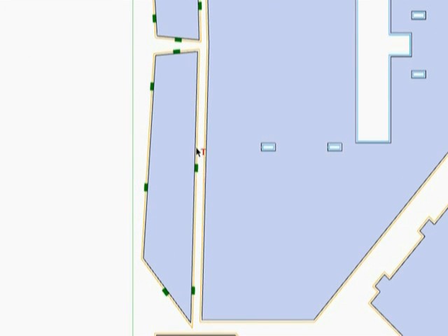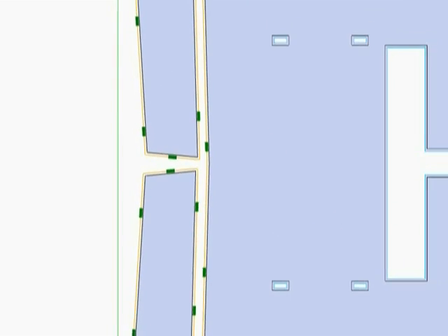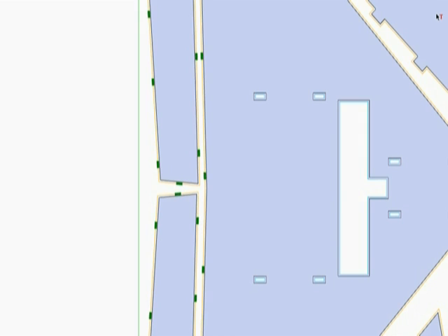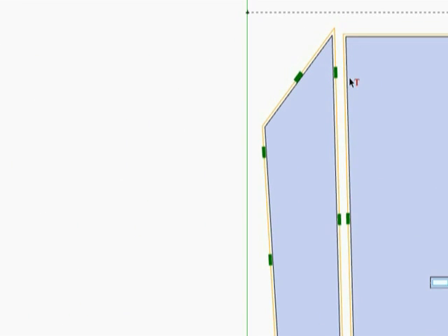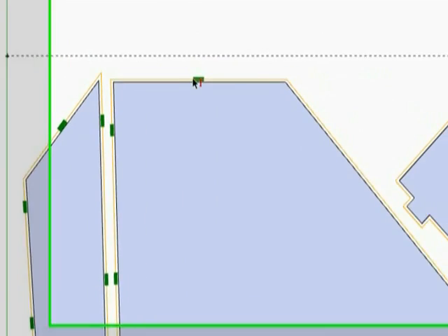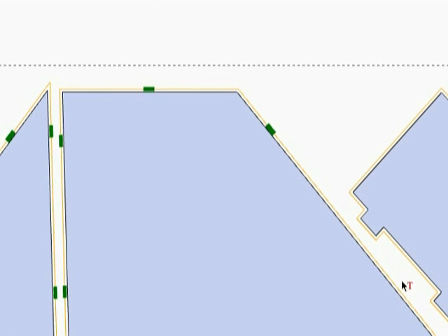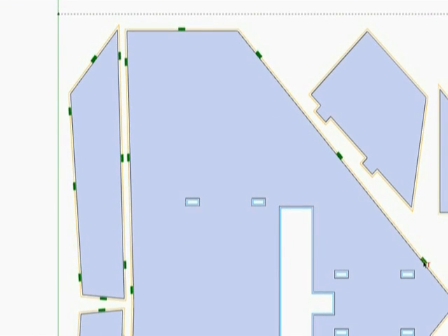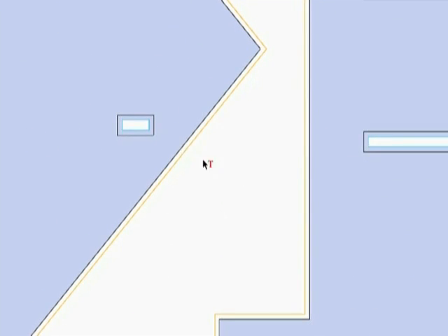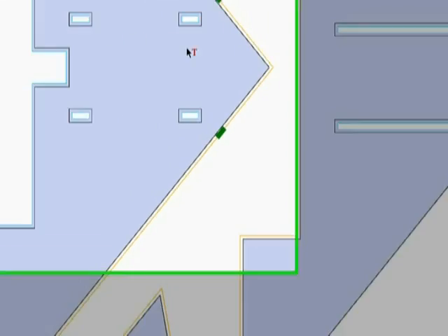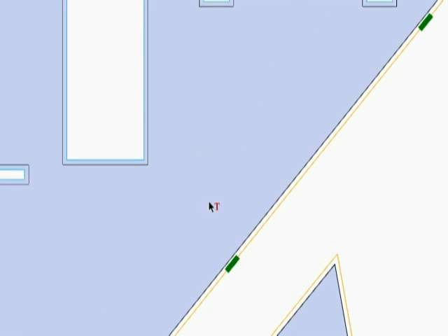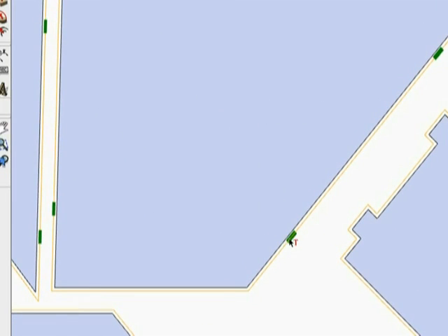Now if you are working your file up and you go out and you cut it and you say, wow, you know, everything worked really well, except maybe this part over here fell out. Well, then you know maybe you need to go back and readdress how you've tabbed it. But I just add just a few here. We'll add them as such. Now I can tell you in other CAM programs, programs that help you to generate machine code.